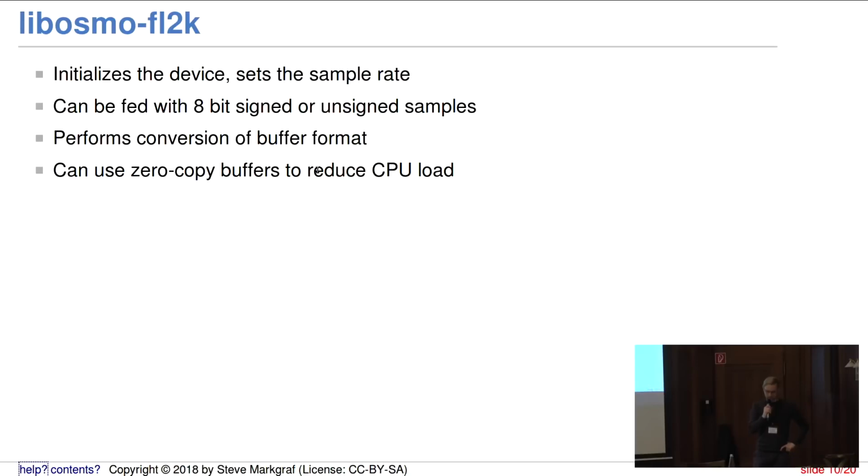And someone also wrote a GNU Radio sink for it, with some modifications inside the library to use I and Q interleaved, so he's just using 2 DAC channels. But this is only interesting if you attach some IQ modulator.